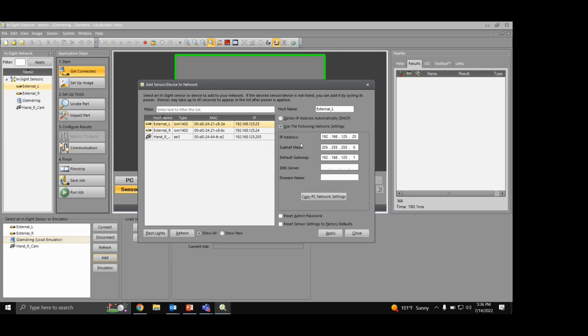Whenever you're talking Ethernet IP communication, it is defined as these 4 values right here. On a local network, you will most of the time see 192.168, and then every group has their own preference on this third value. A lot of times it's either .0 or .1. With ABB robots, it's always .125. So as I said, every group has their own preference. And whenever I'm saying it needs to be on the same subnet, that means these first 3 values need to be the same as the robot subnet, which should also be the same as the computer's subnet. With that in mind, this 4th value has to be different.